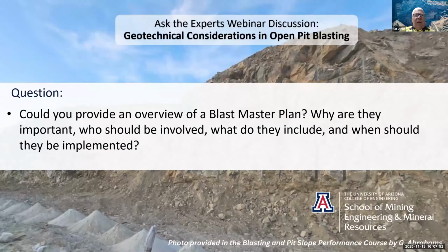And then other things that we need to be discussing during that blast master plan are identifying and quantifying what the performance indicators are and what those objectives are. Things like vibration monitoring. What are the PPV thresholds? What are the frequency thresholds? Are we achieving spatial compliance? Are we getting our toes and crests in the right spot? What are the face conditions looking like when we scale back to final high wall?